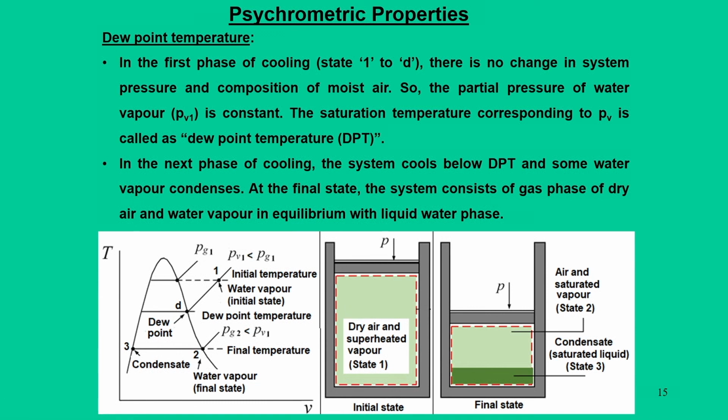So, this is how it is explained here, and typically when you deal with pressure values, you have 3 pressures as of now. Correspondingly, initially we have pressure Pv1, which corresponds to state 1, and at the same initial temperature, if you draw this vertical, we reach this saturation curve at this point, and at that point we have Pg1. Obviously, this Pv1, if you look at this curve, is less than Pg1.